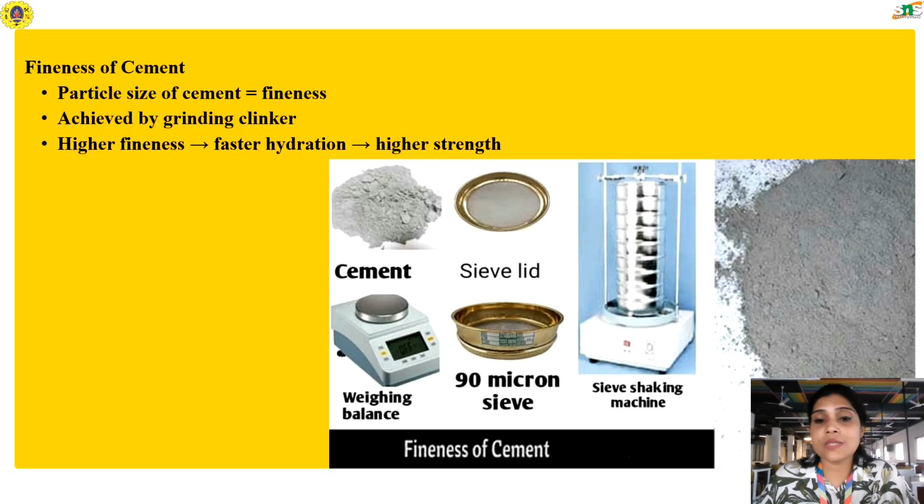If the cement is very fine, the hydration is faster and the strength develops much quicker. That's why in modern construction, especially in high-rise buildings where early strength is important, finely ground cement is preferred. However, there is a balance. If cement is too fine, it may lead to problems like shrinkage and high water demand.